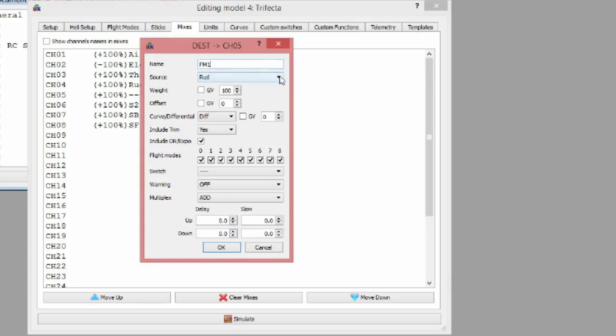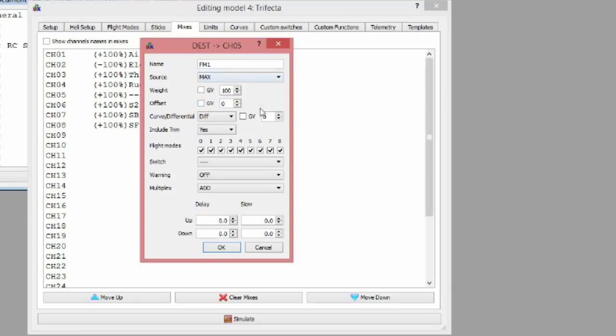It's dependent on either CS, because CS1 is going to be 100%. So I can put it at CS1, or I can use max, which is 100%. We want it to give off a value of minus 60 when triggered, and it is dependent on switch CS1. So there's custom switch 1. When we've got custom switch 1, we want minus 60 out.